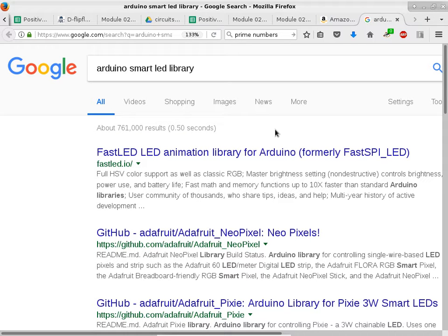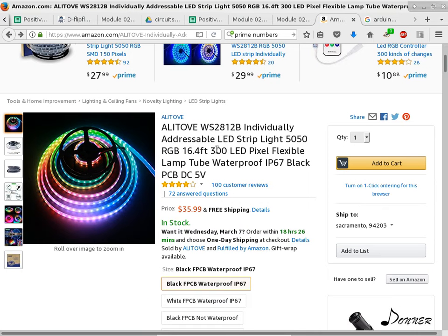So it's very interesting what you can do with this. I just wanted to mention this because we were talking about registers, and this is a very special kind of register where you clock in the content of those registers 1 bit at a time. Because it has a serial nature, you just have to spend more time to clock in more data, and eventually you get to control each and every single LED of the entire strip, which is pretty long in this case. So if you want to make any type of display, this is one way to do it.